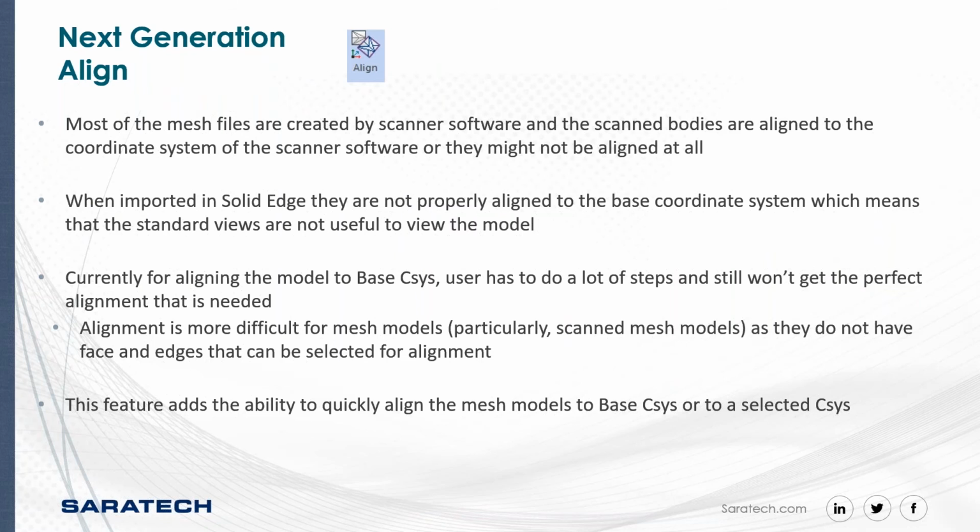So Align is our next new icon that came out. Most of the mesh files are created by scanner software, and scan data are aligned to the coordinate system of the scanner software, or they may not be aligned at all. So when imported into Solid Edge, the data is not properly aligned to the base coordinate system, which means that the standard views are not useful to the view of the model. Currently, to align the models to the base system, the user has to do a lot of steps and still won't get the perfect alignment that is needed.